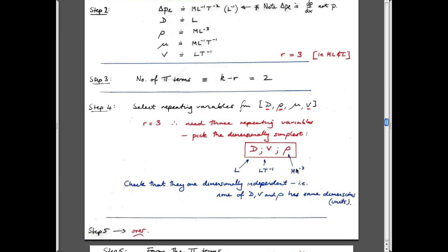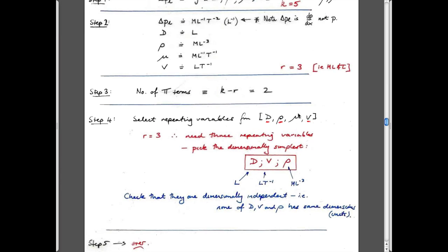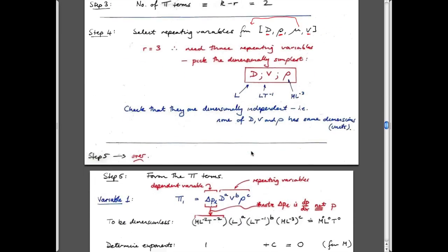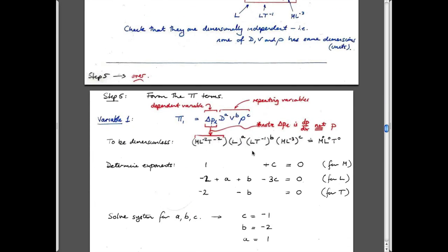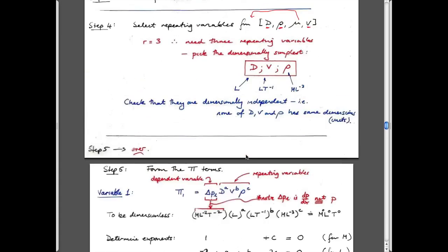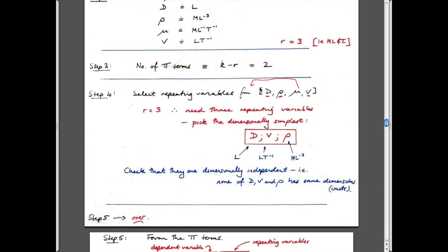And then one dependent variable, which goes out here. And you do the Buckingham Pi thing to it. Really, the big picture is that when you have these 4 parameters grouped together as products of each other, all you're doing is making sure that the exponents come out so that the dimensions of that parameter are 0. So it has no dimensions. That's really all it's physically doing.